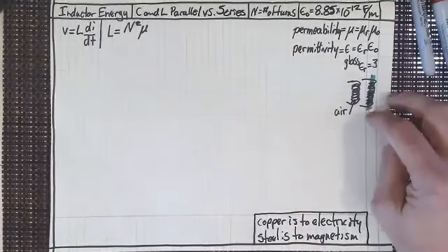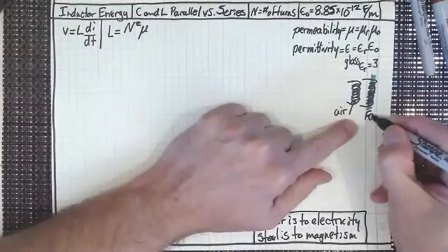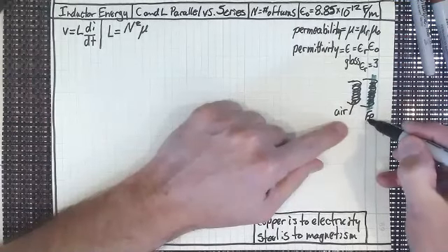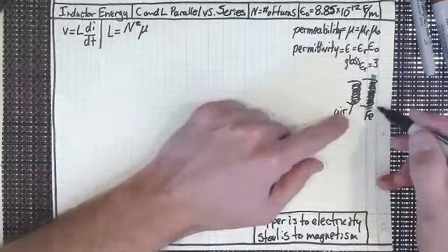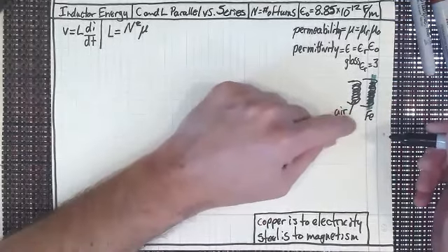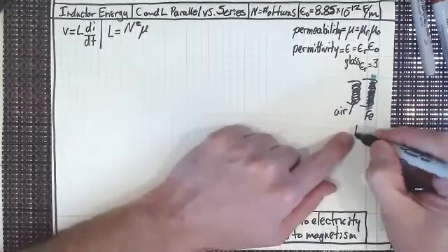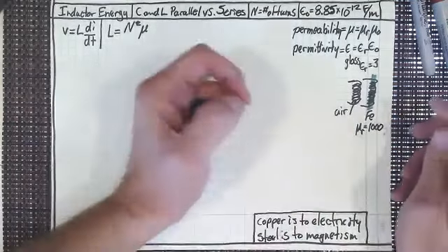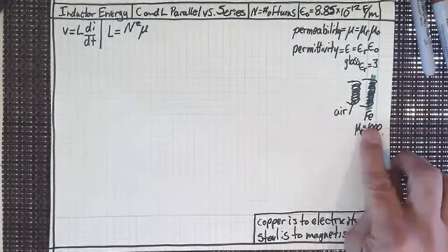And so if I put a steel in there, now what is that? What's the relative permeability? If that is steel, I'll put iron, because basically electrical steel is predominantly almost 100% iron. And it's got about 3% silicon in it. You'll get into that when you start to study motors and controls. Anyway, so that's steel. And what is the relative permeability of steel? It's about 1,000, right? Notice there's no units on there. It's a ratio.